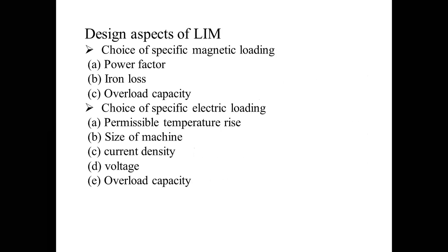And next, we have some design aspects of the linear induction motor. We considered these on the thrust force equation and also some of the performance analysis of a linear induction motor, but mostly on the thrust force equation. That is the choice of specific magnetic loading and the choice of specific electrical loading. These are the aspects we consider while designing any linear induction motor.